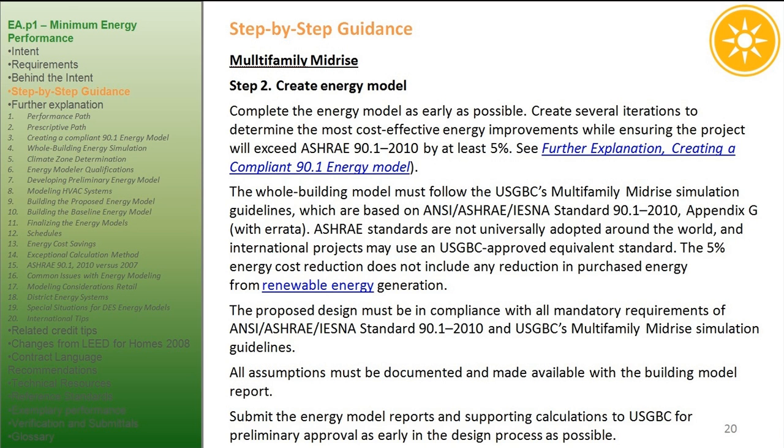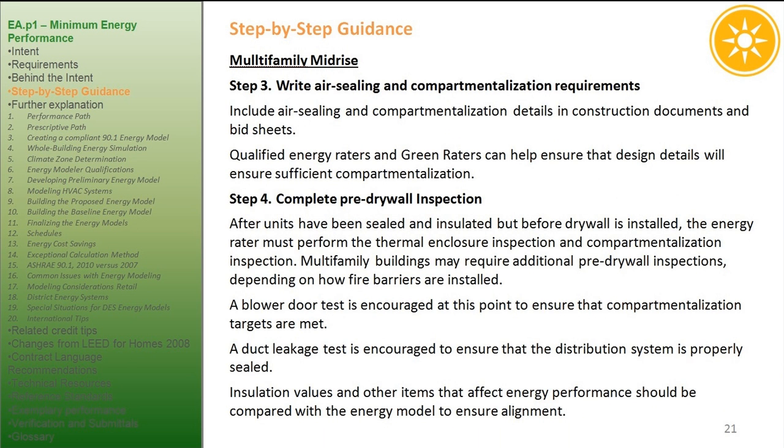The proposed design must be in compliance with all mandatory requirements of ANSI/ASHRAE/IESNA Standard 90.1 2010 and USGBC's multifamily midrise simulation guidelines. All assumptions must be documented and made available with the building model report. Submit the energy model reports and supporting calculations to USGBC for preliminary approval as early in the design process as possible.